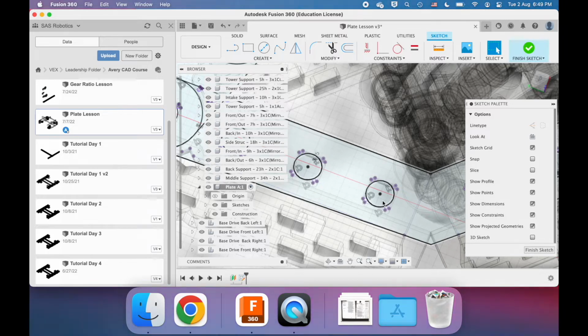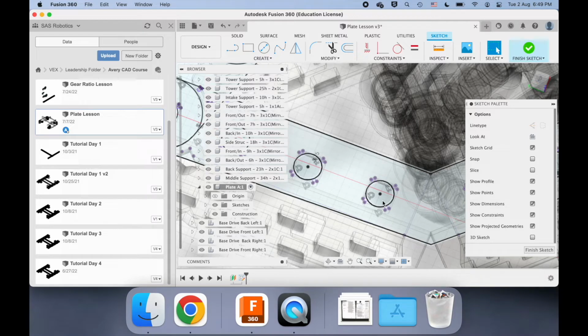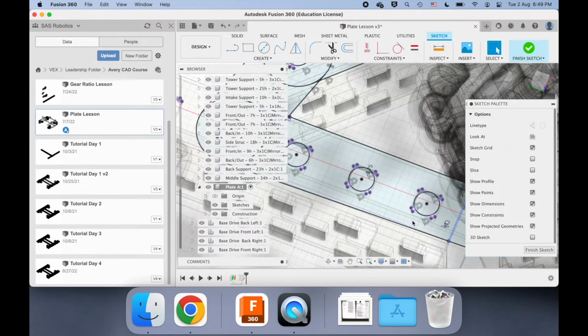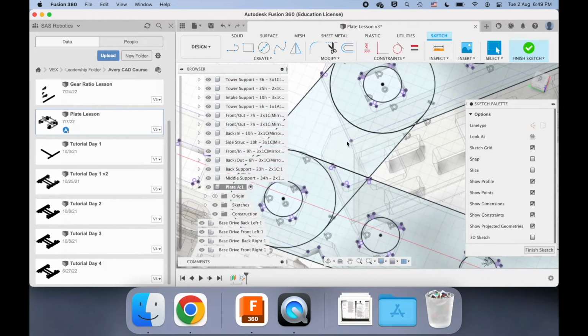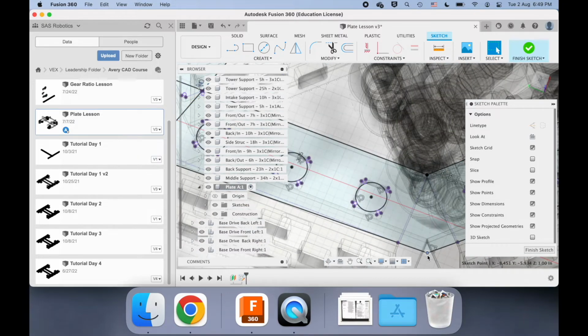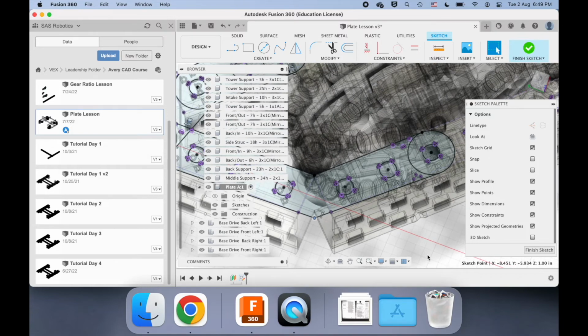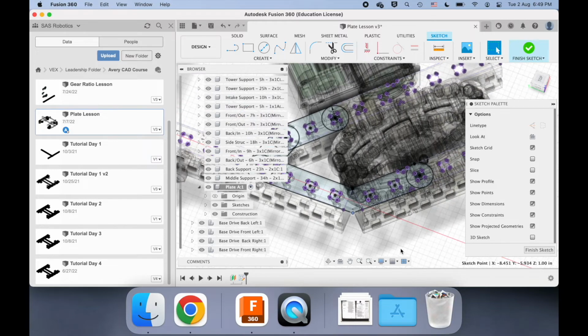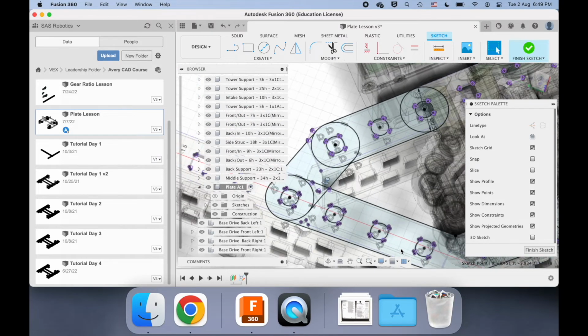And how it works is you put in a sheet of some Delrin. The thickness we use in VEX is 1 millimeter. And the laser cutter goes around and cuts all the pieces out. But all of the corners have to be rounded, otherwise the laser cutter won't do a good job cutting. So right now we have some problems, right? We have a pointy point here, here, here, here. So we need to round out all of these corners to make it cut properly, and it usually makes the plate look better anyways, so that's a plus.